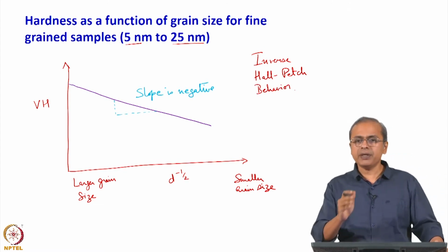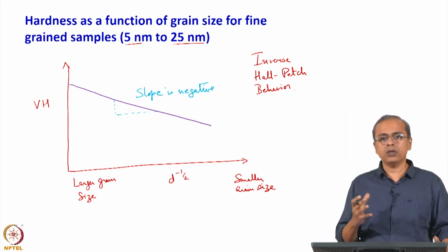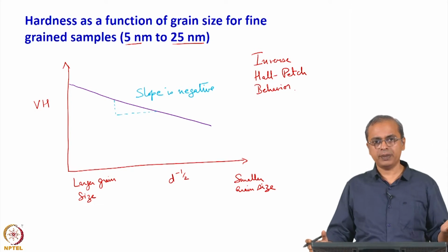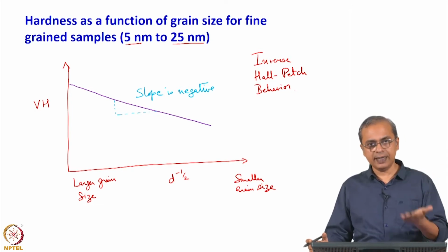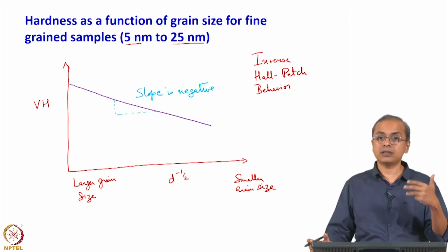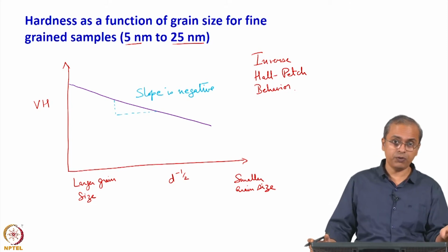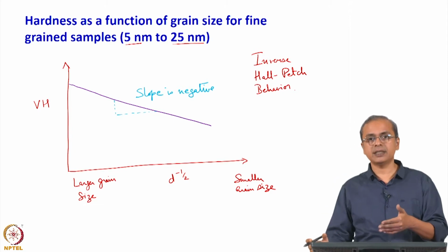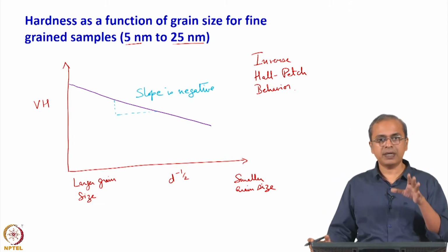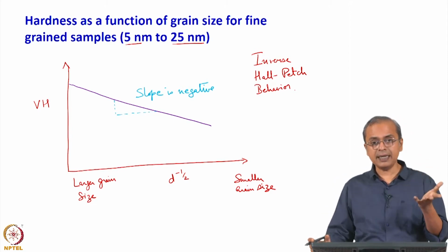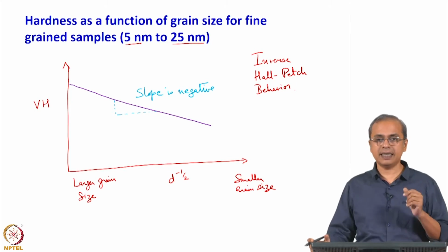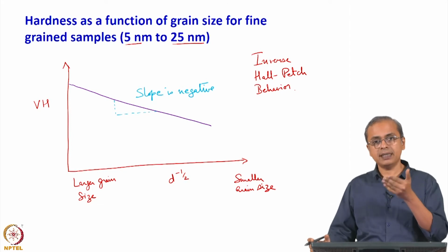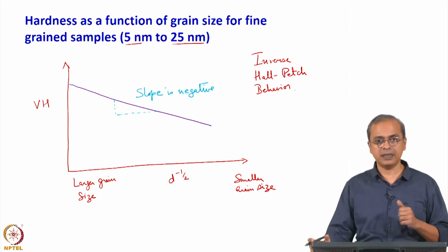So, this is very useful and very important to know, because in all of science that is basically what we do. We look at some experimental phenomena and we try to fit a theory to it. So, some experimental phenomena that has either not been observed before, or it has been observed before, but for which we do not have a good explanation. So, we try to come up with an explanation, we come up with a theory, and so the trend that was there in the grain size related impact on yield strength was a phenomenon that had been explained previously by the Hall-Petch equation.